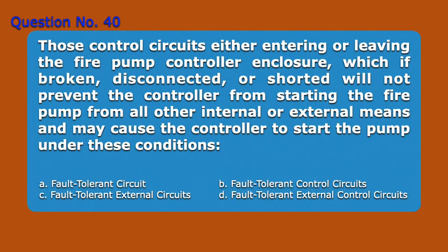Question number 40. Those control circuits, either entering or leaving the fire pump controller enclosure, which if broken, disconnected, or shorted, will not prevent the controller from starting the fire pump, from all other internal or external means, and may cause the controller to start the pump under these conditions. A. Fault-tolerant circuit. B. Fault-tolerant control circuits. C. Fault-tolerant external circuits. D. Fault-tolerant external control circuits. Answer D. Fault-tolerant external control circuits.